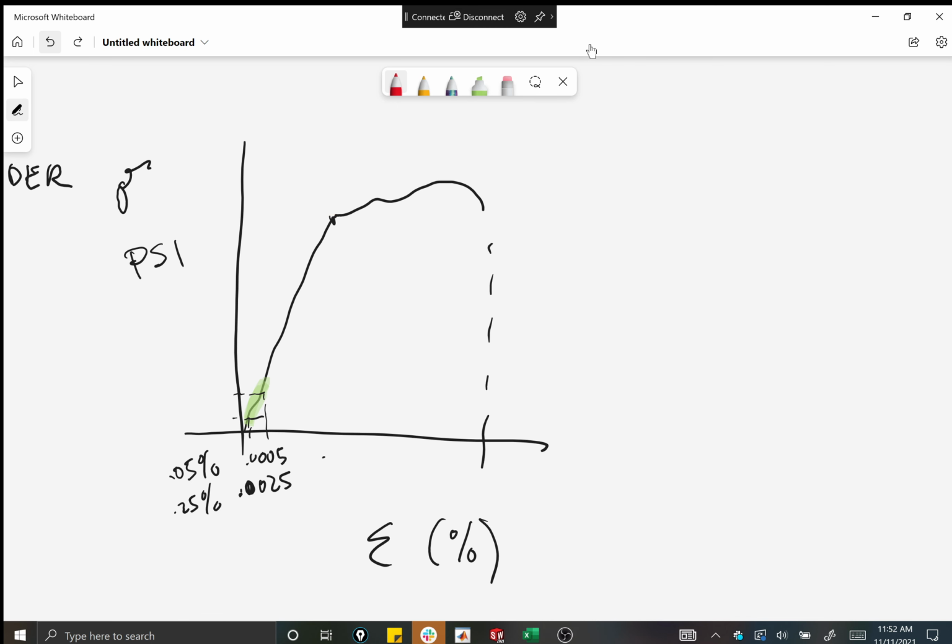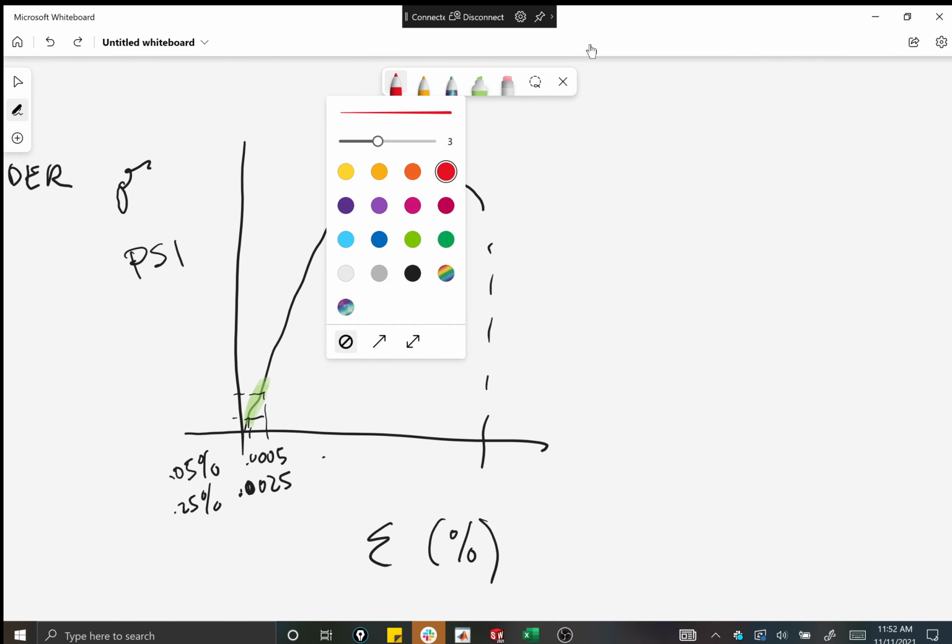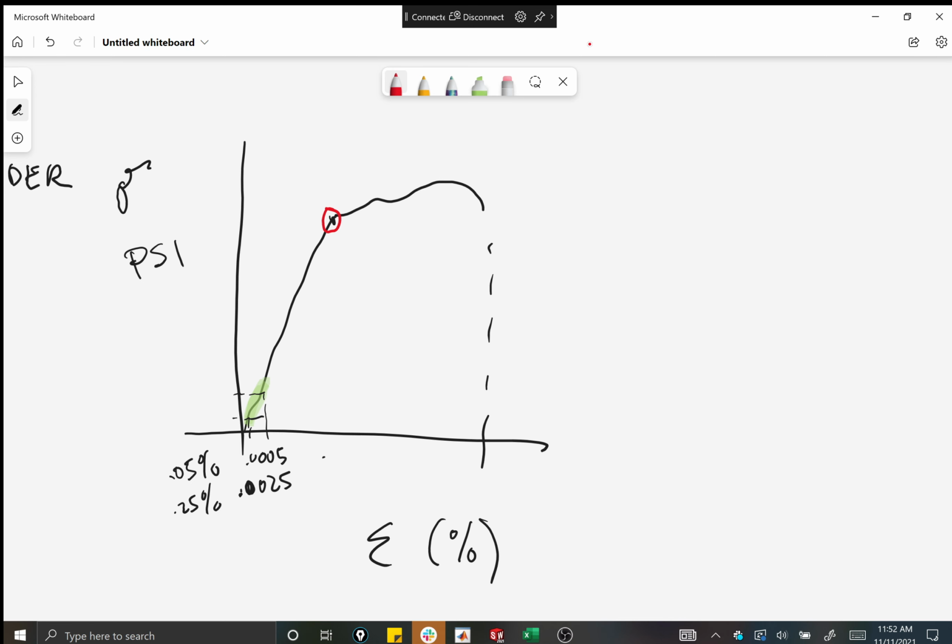related to, because the idea is this. So this continues on. This is the linear. The elastic region is the linear portion of the data curve, and it's linear because it's proportional, right? You add more force, you're gonna get a proportional amount of additional strain, and that's why this is also called the proportional limit. So that's either the yield point or the proportional limit.